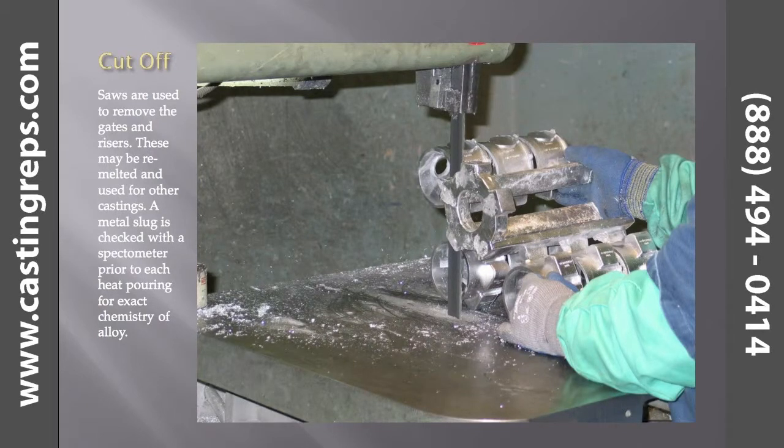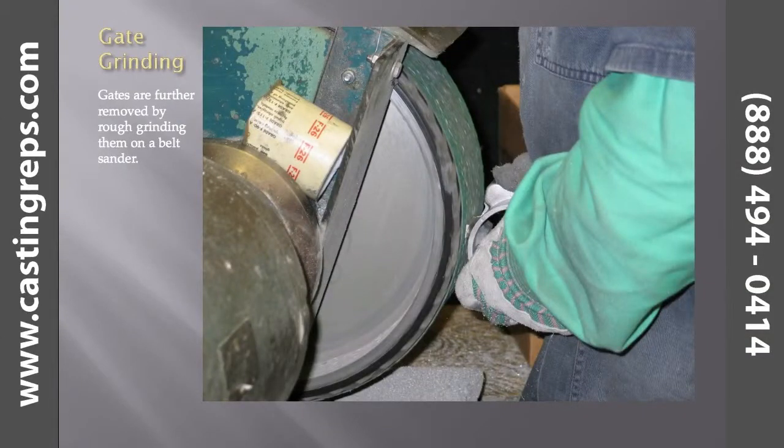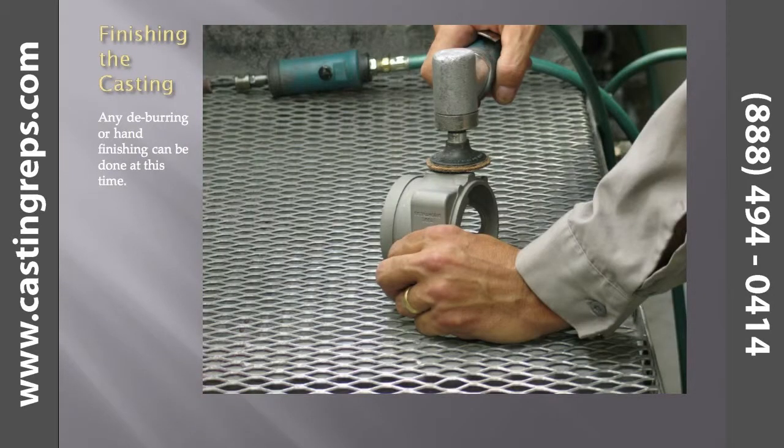Cut-off. Saws are used to remove the gates and risers. These may be remelted and used for other castings. A metal slug is checked with a spectrometer prior to each heat pouring for exact chemistry of alloy. Gate grinding. Gates are further removed by rough grinding them on a sand belter. Finishing of the casting. Any deburring or hand finishing can be done at this time.